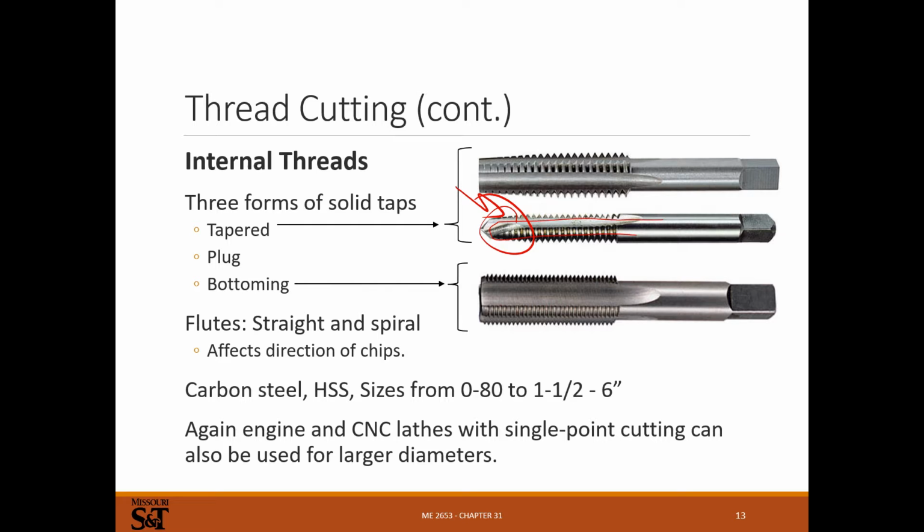And the main thing is to not side load the tap. Even if you're putting a pure torque on it, you can still break them, usually because you haven't broken the chips or you're working too aggressively. A lot of times if you're tapping by hand, you'll side load the tap and just snap it, especially the thinner taps. So you need to make sure you're not side loading.